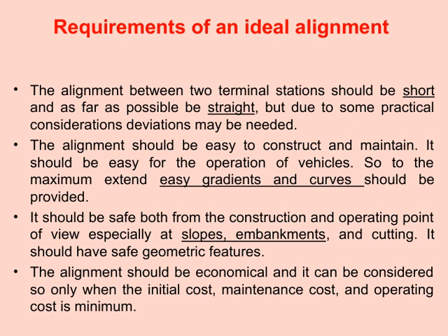It's also crucial that the alignment is easy to construct and maintain. This ease of construction directly impacts the overall project timeline and budget. From an operational perspective, vehicles should run smoothly, which means designing easy gradients and gentle curves wherever possible. Sharp bends or steep slopes can cause operational difficulties and safety issues.